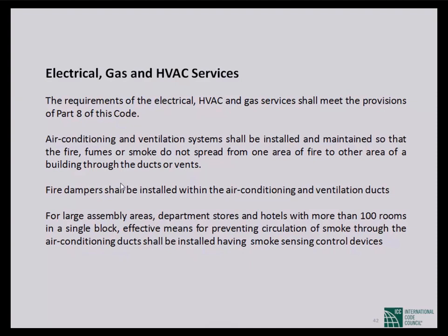Another thing, for large assembly areas, departmental stores, hotels with more than 100 rooms in a single block, effective means of preventing circulation of smoke through the air conditioning duct shall be installed, having a smoke sensing control device. So you have to be very careful about the design of these assemblies. You need to consider smoke sensing in a different way, particularly for large hotels and departmental stores. That area is different.